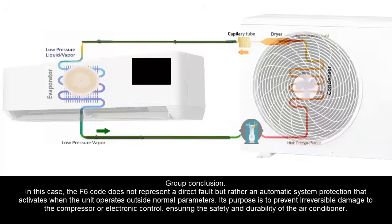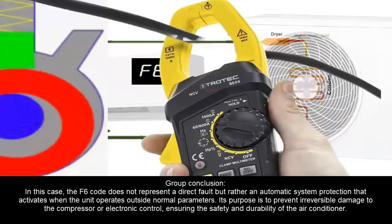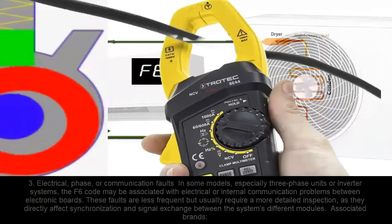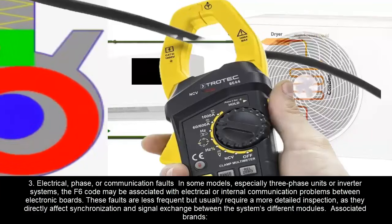Group conclusion. In this case, the F6 code does not represent a direct fault, but rather an automatic system protection that activates when the unit operates outside normal parameters. Its purpose is to prevent irreversible damage to the compressor or the electronic control, ensuring the safety and durability of the air conditioner. 3. Electrical, phase, or communication faults.